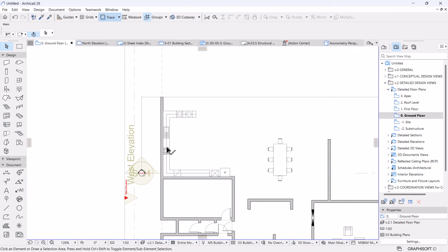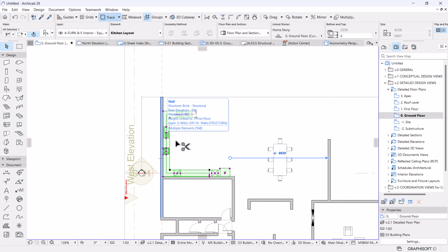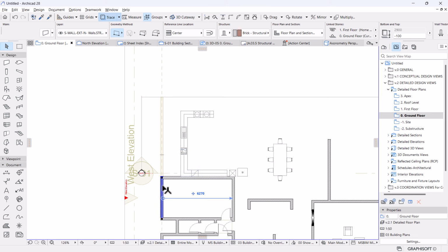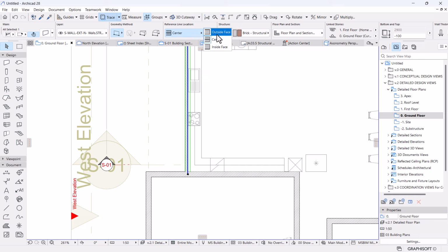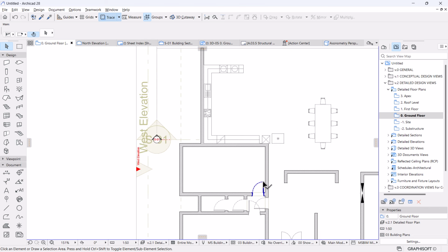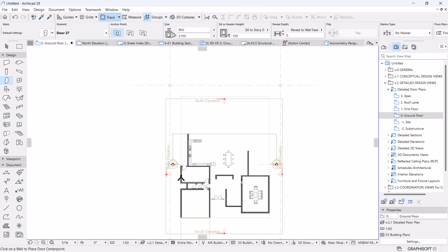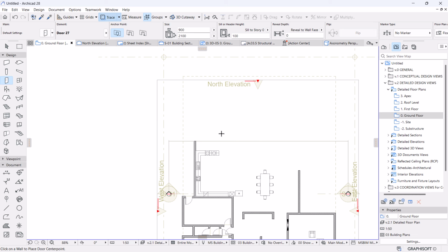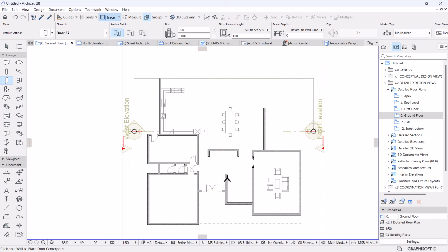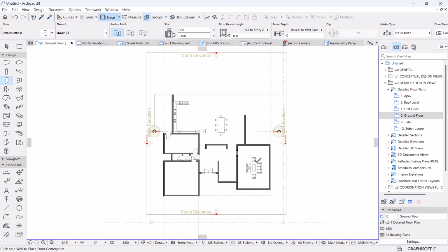Okay, so that's basically how you can quickly set up your kitchen. But I wanted to have more like a patio or a lobby this side, so I'm going to offset this by 126. Then I'm going to trim this, pick the perimeter of this wall, then have it there. Perfect. So instead of positioning it on the center, I'm going to reference from outside and then flip it that way. Okay, so that's basically what we have there, so that I can have another access for the staff from the outside, because there I can provide your laundry and scullery, so that she can just go right straight into the kitchen without going around to the other side of the house.